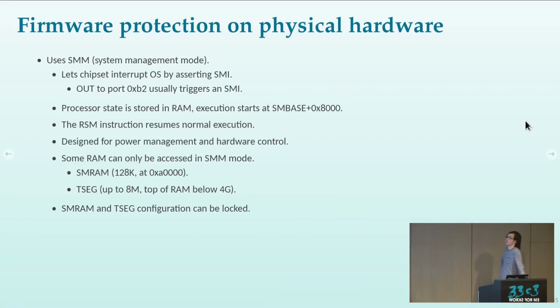The chipset can send an interrupt to enter system management mode, and the processor will store the complete state of the processor in memory and start execution at a definite address. And with a special instruction, it can return to normal operation.